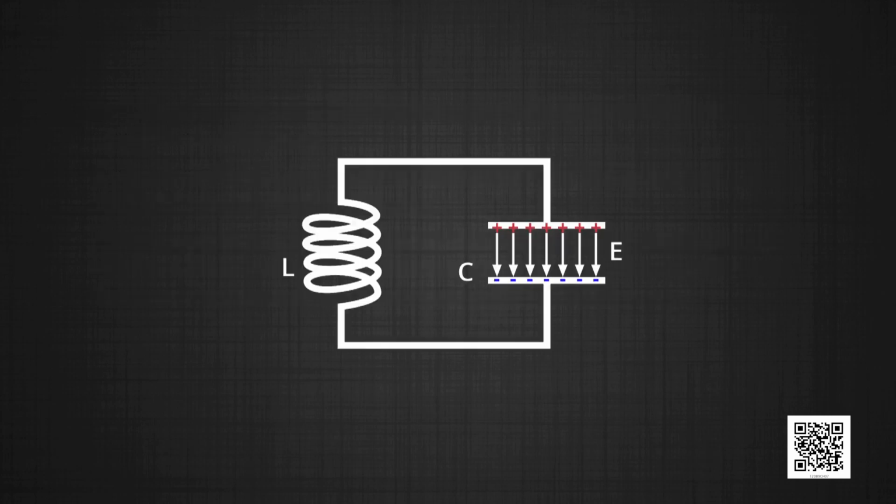So, look at this diagram, what do we observe? Here we have an inductor and a capacitor. What is happening here? The charge flows back and forth between the plates of the capacitor through the inductor. The energy oscillates back and forth between the capacitor and inductor until internal resistance makes the oscillation die out. In most applications, the tuned circuit has alternating current applied to it, driving continuous oscillations.